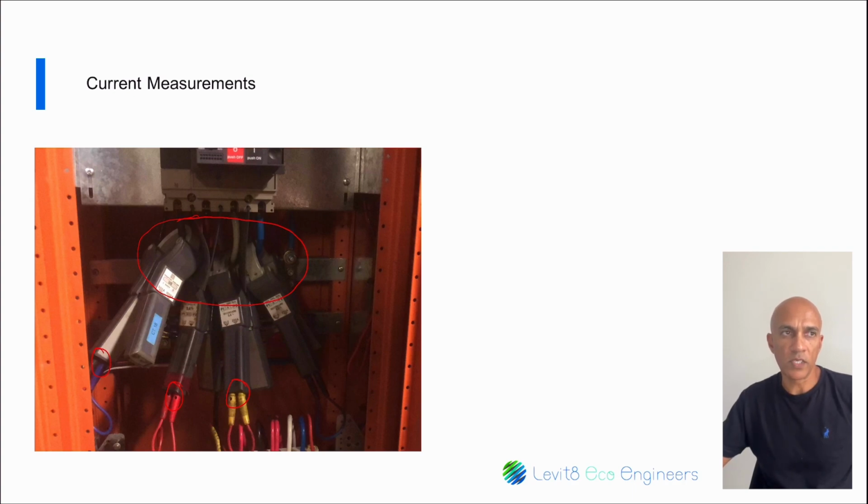That is very important because the short increase in load could be even half a second, 1 second, but averaged over 5 minutes, it looks like there hasn't been a sharp increase in the load. So it's very important that you also select maximum values.